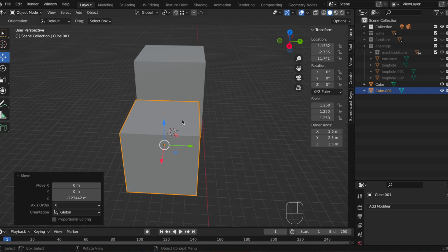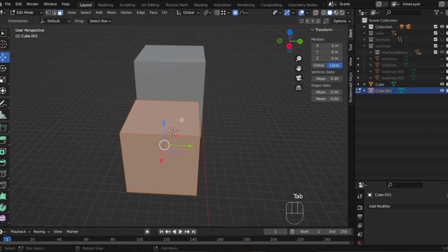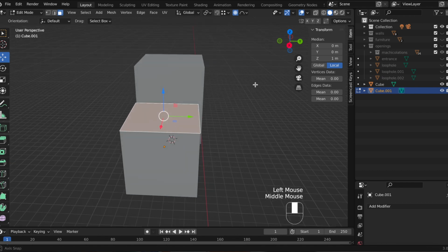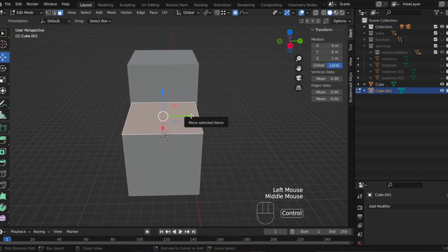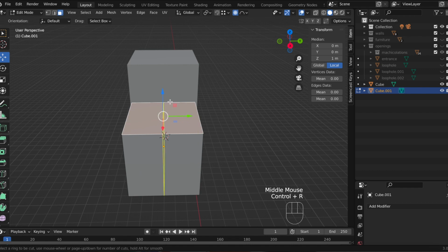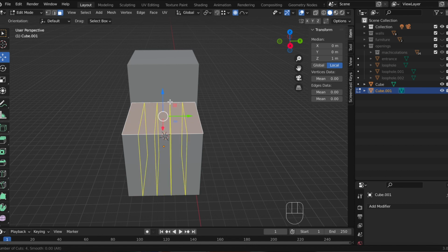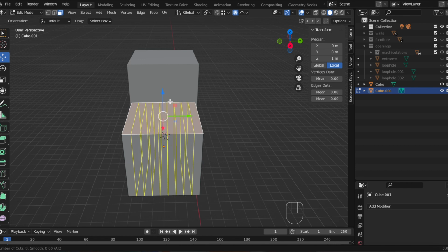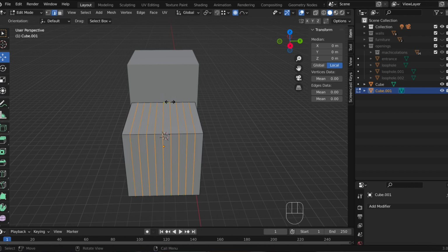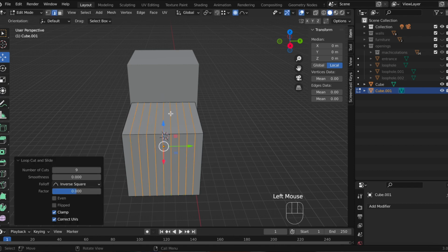In order to recreate this vaulted soffit, probably a barrel vault, so with a hemisphere, we select the top face and with Ctrl R create our cuts. With 9 cuts, we ensure that the shape is smoothed out more. It is convenient to choose an odd number, as we will then need the center edge that will act as the keystone of the vault.